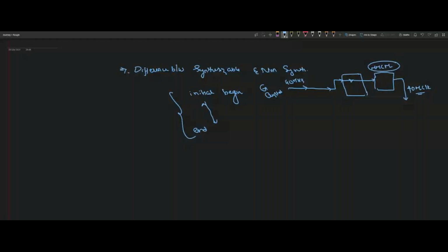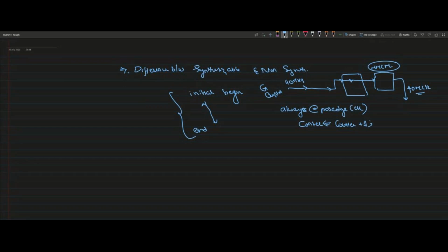One always block has to maintain a delay of 10 milliseconds. Next, we need to go for a functional block of the actual design. Always at positive clock edge, and go for a counter. The counter has to count for a particular 10 milliseconds. So the counter keeps incrementing: counter equals counter plus 1, right? So how do I know that it reached 10 milliseconds?